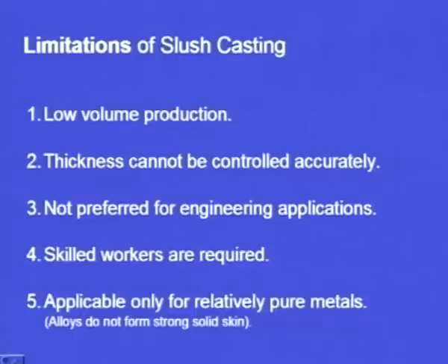If the skilled worker is not there, he may pour it before time, in which case the whole metal will be drained out. If it is delayed a little, the entire metal may solidify and we may not get a hollow casting. The purpose is lost. So skilled workers are required, and this process is applicable only for relatively pure metals, because alloys do not form a strong solid skin.